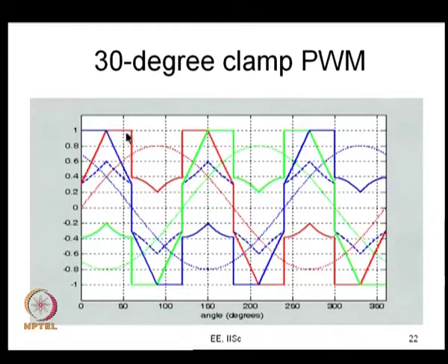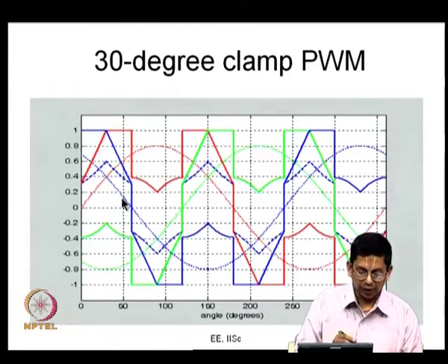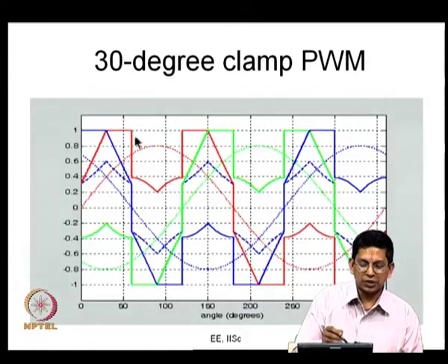So here again the switching frequency is 0, here again the switching frequency is 0, here it would switch at carrier frequency. Once again, for 60 degrees it is not switching, 30 degrees here and 30 degrees here, and your average switching frequency will be 2/3 times Fc, where Fc is your carrier frequency. So we would go to advanced bus clamping PWM, where you will not just have these two cases, that is, switching at carrier frequency and switching at 0.